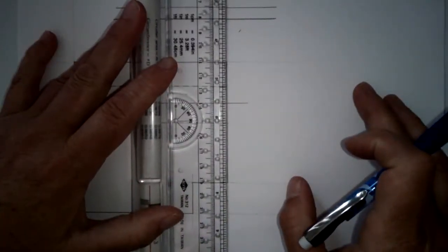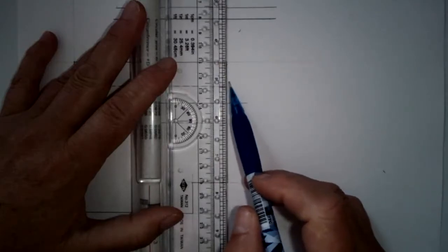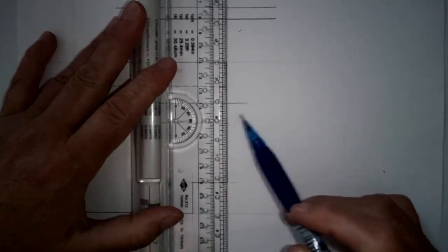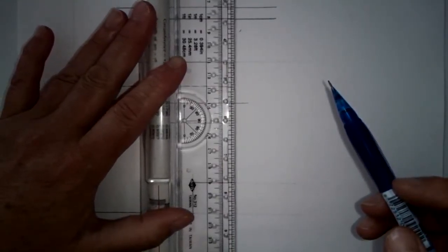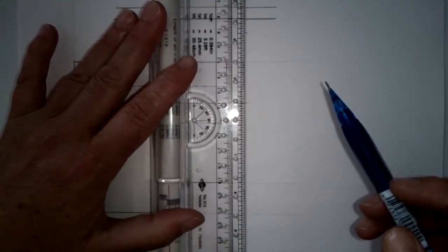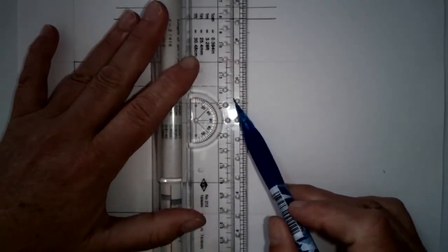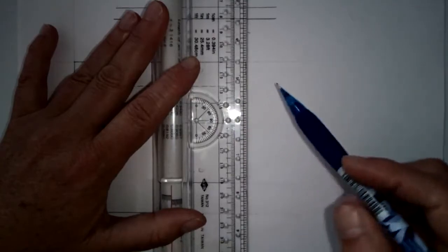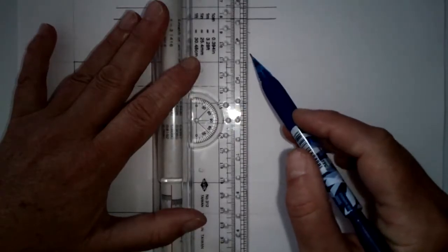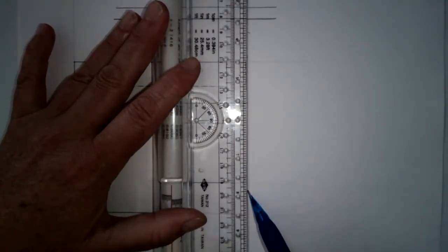And I need to set a consistent distance for my dimensions. So the first dimension off of the part, I'm lining up my straight edge here with the edge of the actual part, should probably be just about to where the end of these longer tick marks are. And I think that's just about a 1/2 inch. So it's a 1/2 inch from the part.